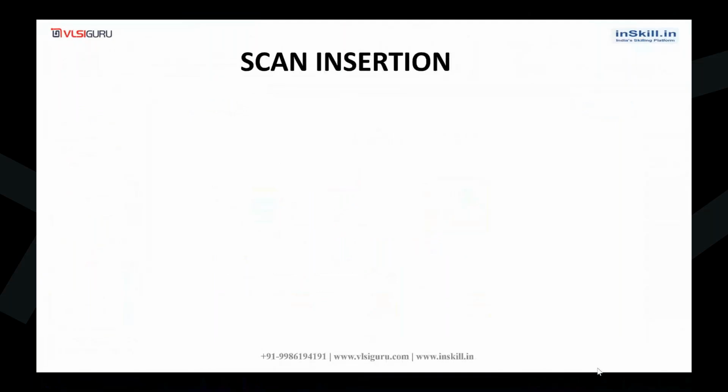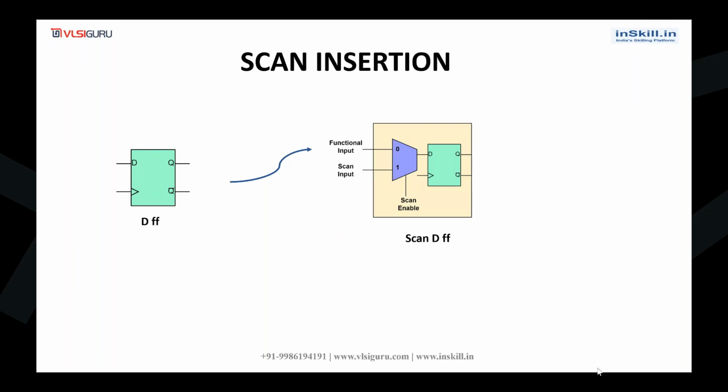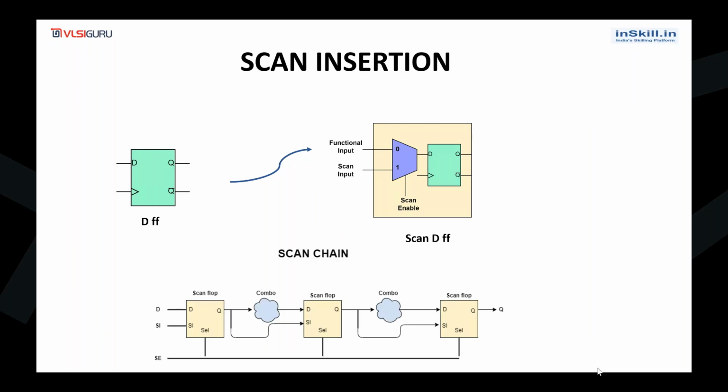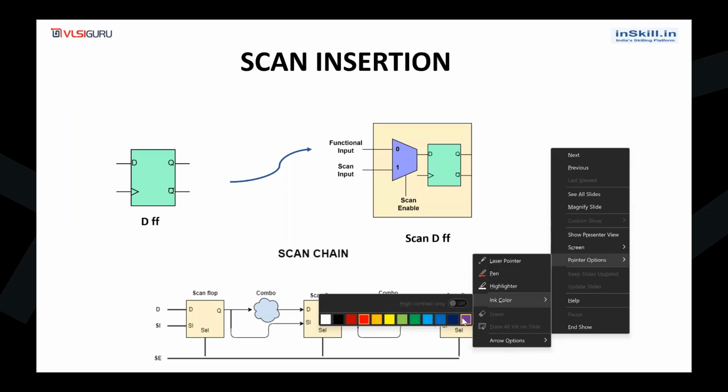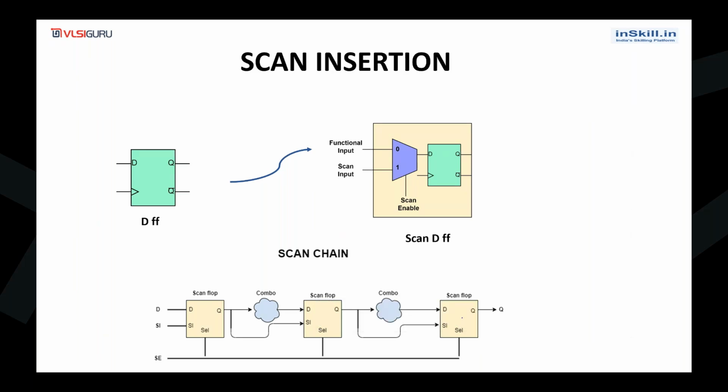So first, let us try to understand what is scan insertion. All the normal flops in the design will be converted into scan flops, and these scan flops will be stitched into a scan chain.